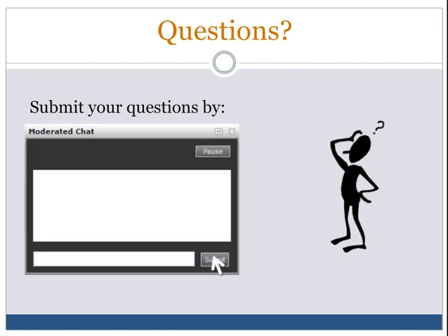Okay. Mike, what is the best way to check for volatile organic compounds for air quality? So basically, for air quality and volatile organic compounds, our biggest recommendation is to use photoionization detectors. It is a very good technology that is capable of covering a very broad range of different ionizable volatile organic compounds.